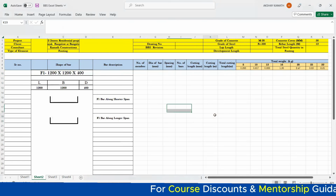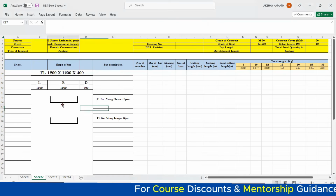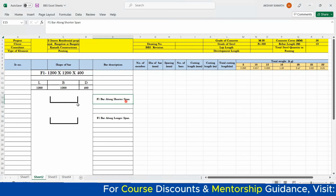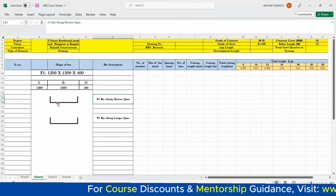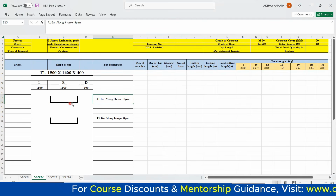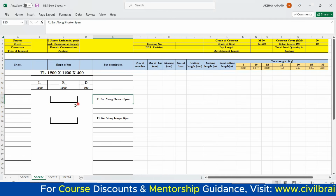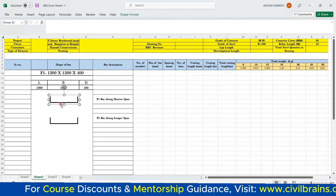Fine, enough. So now you know how to find the cutting length. How do you find the cutting length? Tell me. This is the shorter span bar, right? How do you find this length? So this length will be how much? 1200 minus 50 on the left side, minus 50 on the right side, isn't it? Right. So how do you write it?